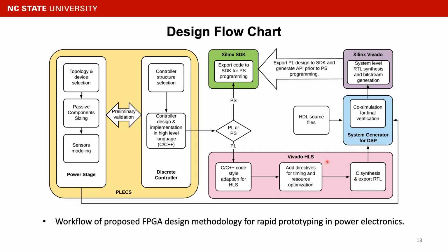Once we have our HLS design, the next step is to run a second round of validation. To do that, we can put all our design into the System Generator for DSP environment. In this toolbox, we can export our HLS design, and also we can include HDL source files like Verilog or VHDL files in the same environment.